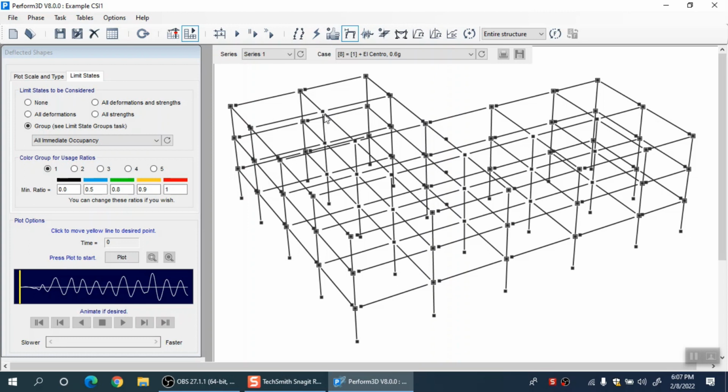Actually think of the analysis in terms of the governing equation of motion. If for example you model water in your computer model and run a static analysis, no inertial effects will be accounted, right. So both of the things should be met. Your model should have that capability to simulate inertial effects, and your analysis procedure should have that capability also, right.